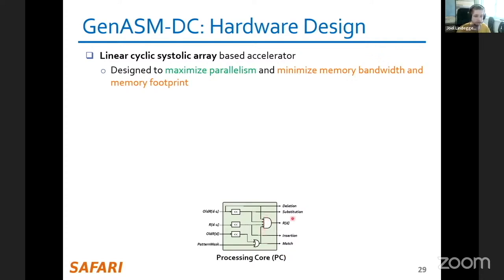This is just a single instance of this, and all of these are 64-bit wires, I guess. But it's really efficient in hardware. In fact, these bit shift operations, in hardware, are not even operations. A single bit shift in hardware just means you move some wires over, so you could even ignore this part. And then it's just a 4-input AND gate and a 2-input OR gate. So at the lowest level of hardware, it's really efficient.